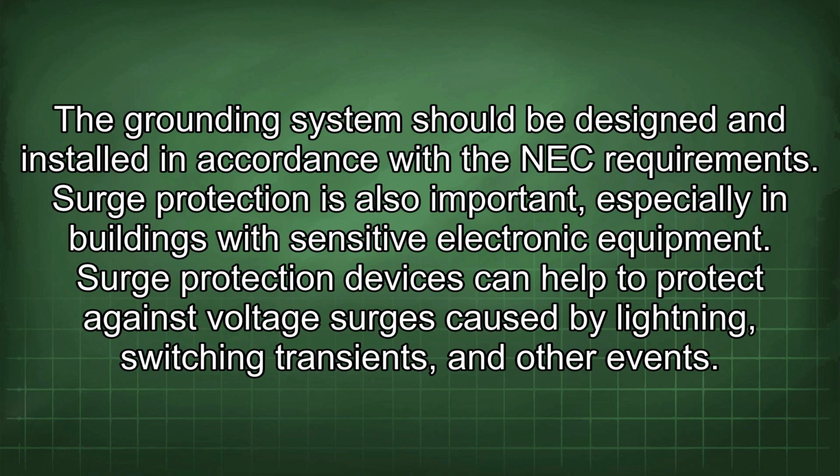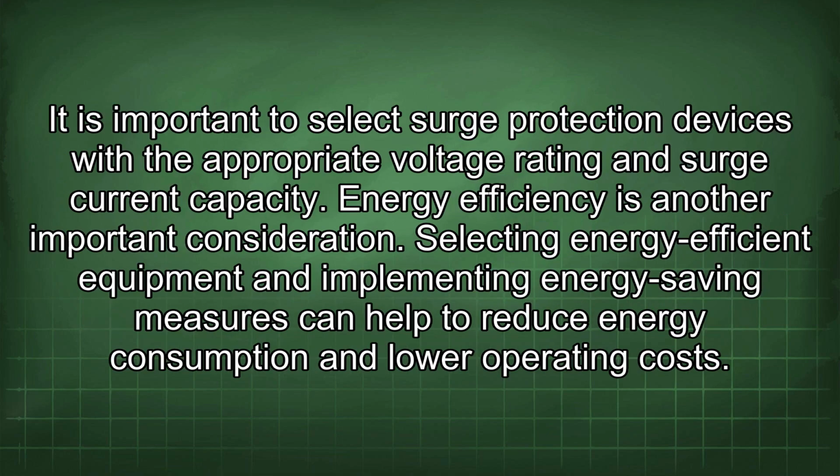Surge protection is also important, especially in buildings with sensitive electronic equipment. Surge protection devices can help to protect against voltage surges caused by lightning, switching transients, and other events. It is important to select surge protection devices with the appropriate voltage rating and surge current capacity.